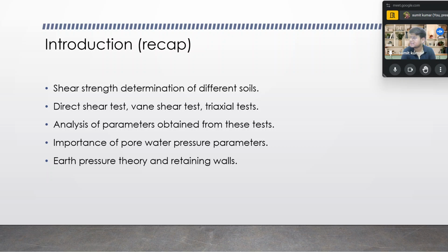Some limitations are mentioned: the test cannot be performed if the soil particle size is large, like if boulders or coarse particles are in the soil. And the large box shear test apparatus is also there.